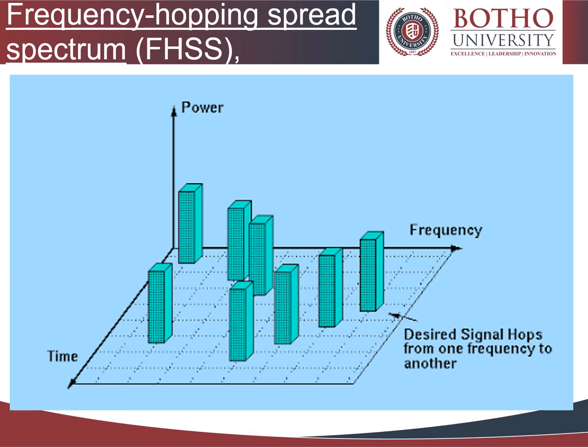At one moment, the signal modulates one carrier frequency, and at the next moment, the signal modulates another carrier frequency. FHSS is a method used to rapidly switch transmitting radio signals among several frequency channels. The FCC has certain regulations with which RFID readers must comply in order to transmit 1 watt of output power.